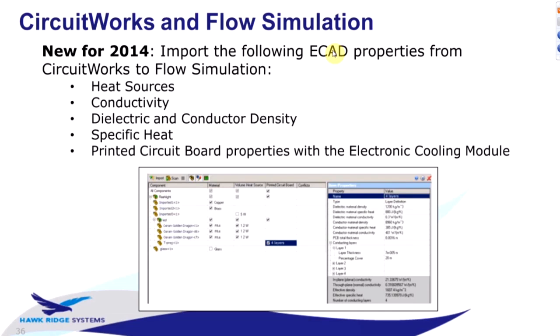So all those values like the heat source, the conductivity of the material, and the specific heats, and all of those printed circuit board properties, they can be imported directly into the setup conditions of flow simulation. And it's also very useful if you plan to go back and forth between SOLIDWORKS Flow Simulation and your ECAD design tool, where you'll be re-importing the model multiple times, which will save you a lot of setup condition time.